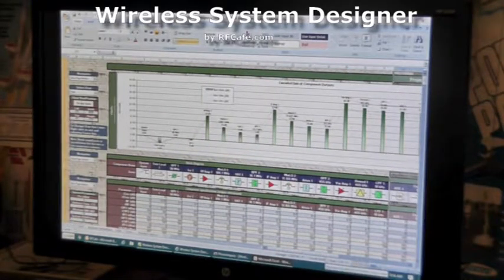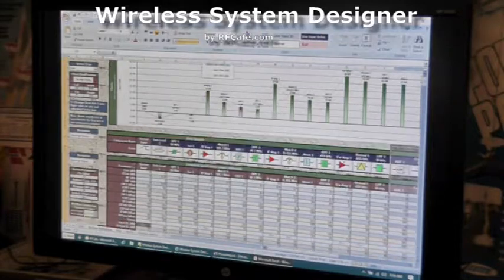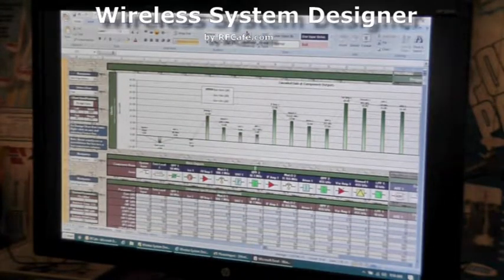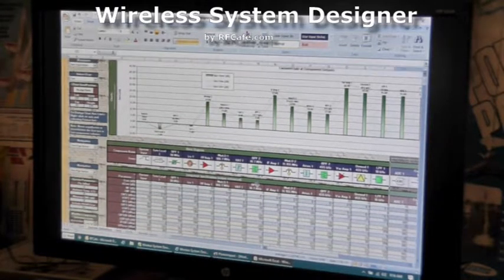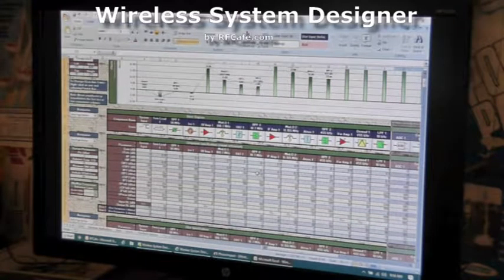So rather than going to the trouble of deleting or inserting columns, I recommend just hiding the ones you don't need. And if they happen to be in the middle of the cascade structure and you just don't want something anymore, say you don't want that filter in there, you can just put no effect or null values in these cells, like make the gain 0, noise figure 0, the intercept points, make them some big number like 200 or 250, something like that, so that it has no effect on the cascade.